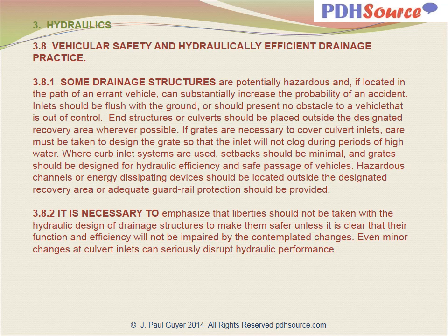It is important to emphasize that liberties should not be taken with the hydraulic design of drainage structures to make them safer unless it is clear that their function and efficiency will not be impaired by the contemplated changes. Even minor changes in culvert inlets can seriously disrupt hydraulic performance.